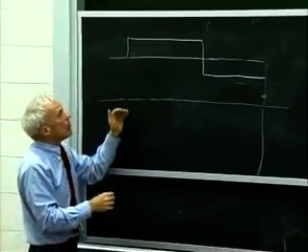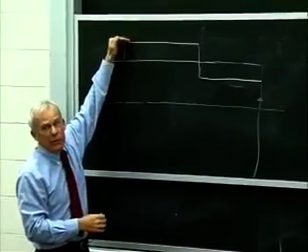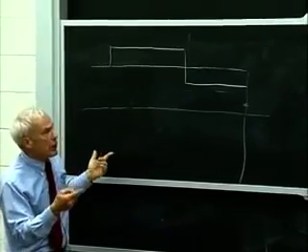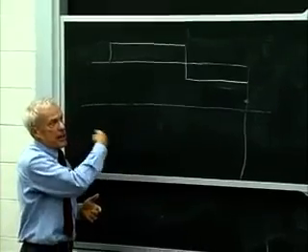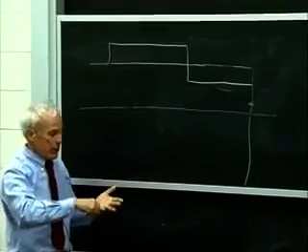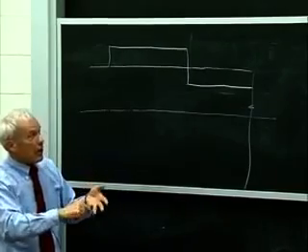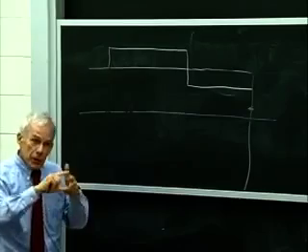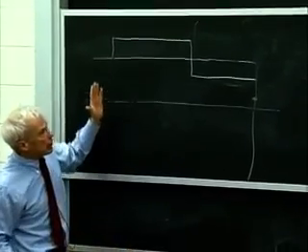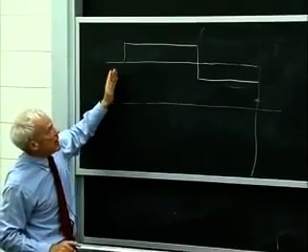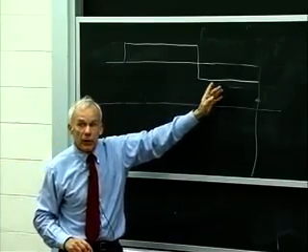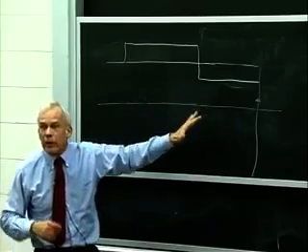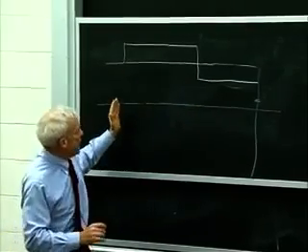It's a bang-bang controller. It's always using the maximum amount of force that's available to you. And in the case of the so-called double integral plant, this is an F equals ma problem where you're controlling distance to go and velocity using acceleration as the control variable. So it's a so-called double integral plant, and the optimal solution for that is two periods of constancy of the control will get you there. And so this is intuitively a well-known example of time optimal, minimum time to get from here to here.